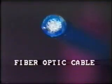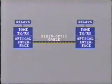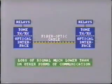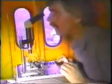Obviously, the inner surface of the fiber has to be reflective, and its surrounding cladding is specially made to prevent or at least reduce loss of light. An advantage of modern fiber optic communication is that the attenuation of signal, that is, the loss of signal, is much lower than in other forms of communication. The fiber optic cable is made of glass or silica or a special plastic. It is very expensive, and so it must be handled with care during installation or repair. Special splicing techniques are required to join sections of cable.